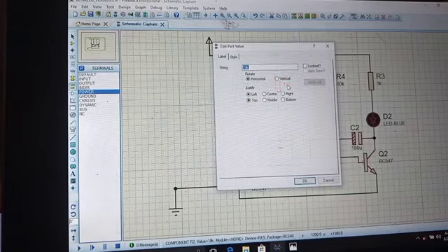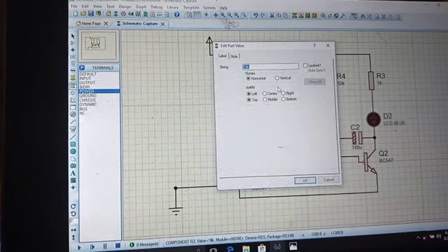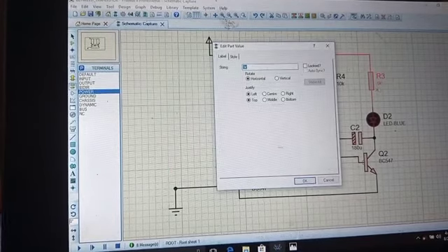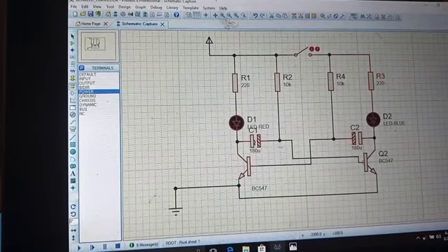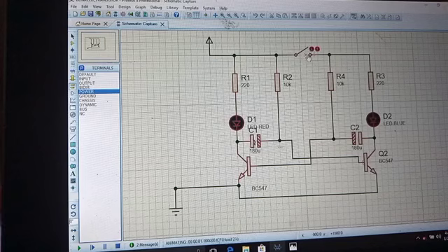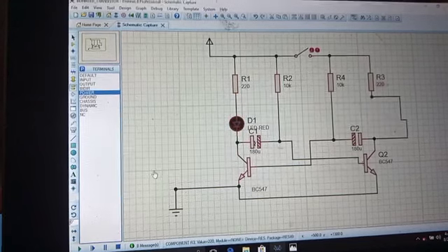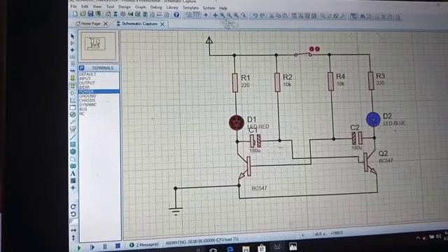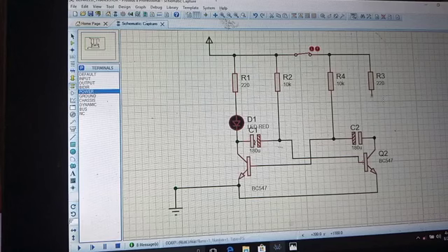Then this time we have to replace our resistors from 1K to 220, since we are using a 12 volt supply that time, in order for the LED to come on bright, because the 1K will not be that bright. So there are many ways. There's still another place to go, down to source, that generator. You can still pick power there.